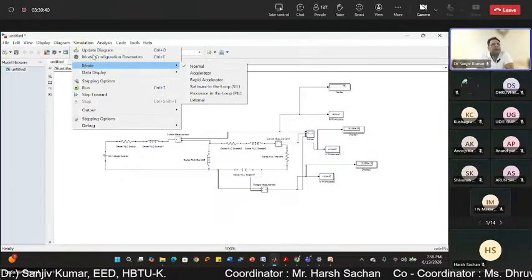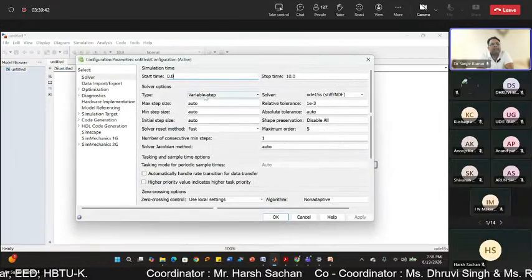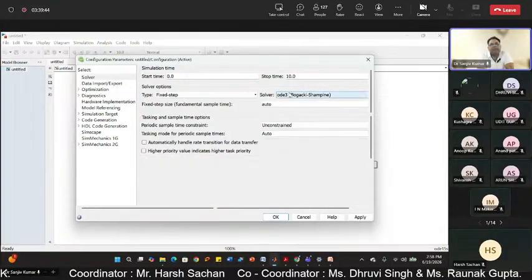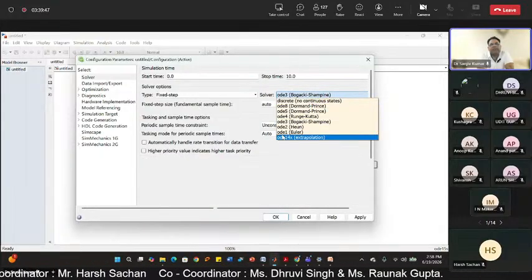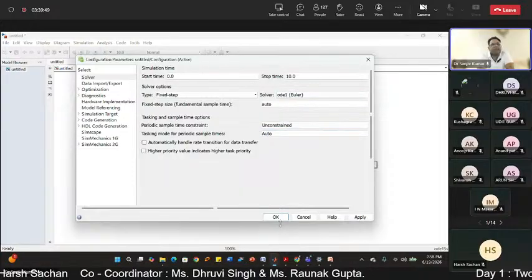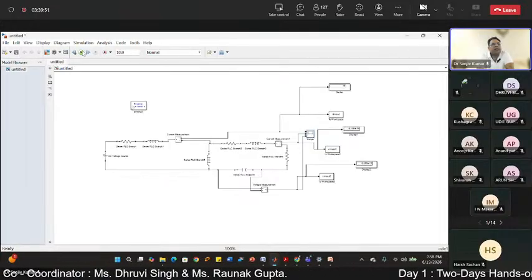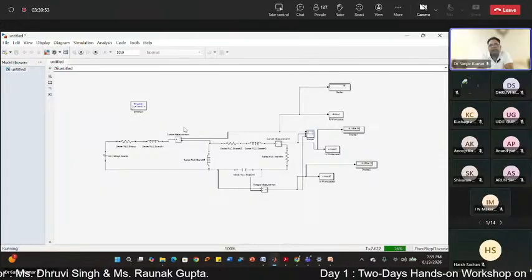Just give me a second. Go here and let us make it fixed step with ode1, right? And see how the response is changed.